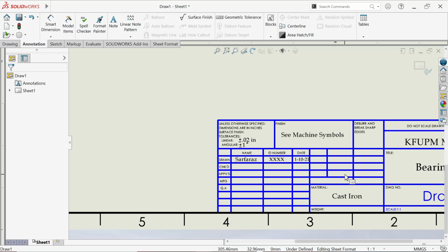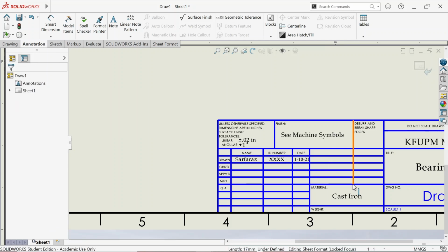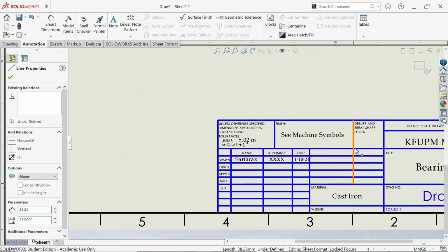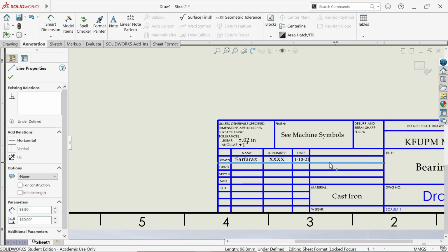We have a third angle projection mode, as the symbol for it is to be included in this particular title block. So let's create some space here to add that. I will delete this line here, hold the line endpoint and drag it a bit up to create space, and these lines we pull to the left.